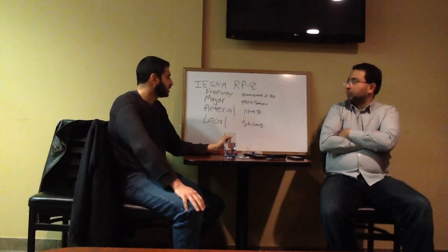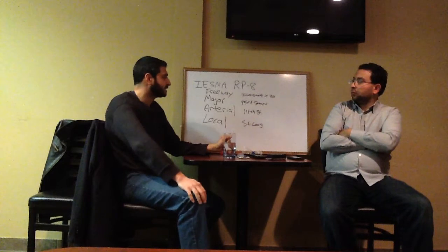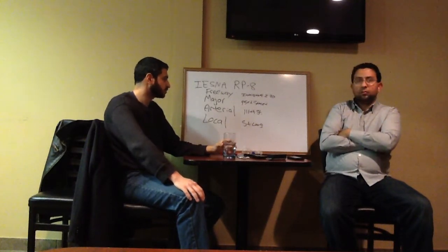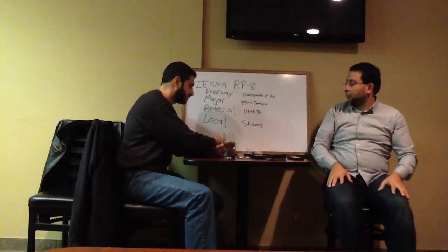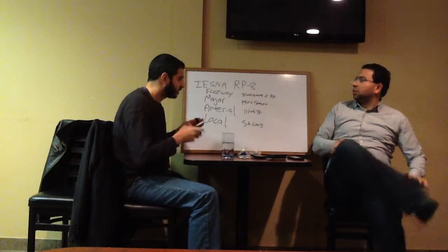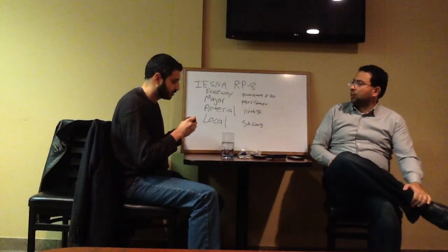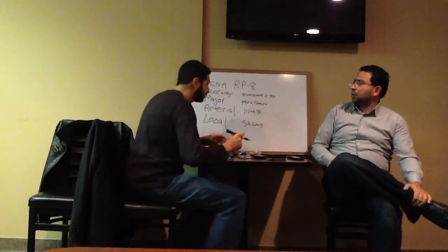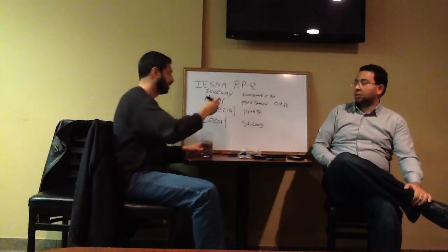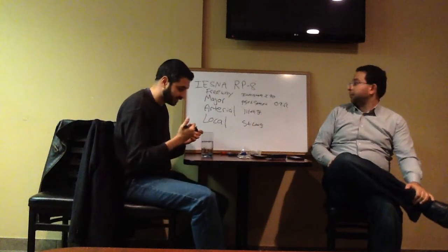So the next point is that you want to figure out the light spacing you want to use. Let me give a random example. This isn't necessarily what's written in the RP8, because I don't have it with me. Let's say we need 0.9 foot candles, based on what we looked up in the guidelines.